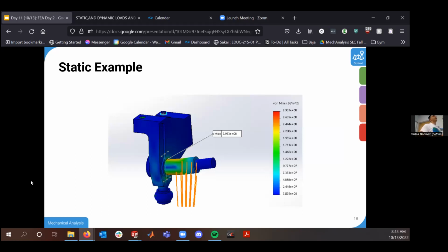This was a knuckle I did. Yeah, I very explicitly found that just for you. Here's a static load of a Baja knuckle turning, and we were looking at the spindle stress right there to see how much light weighting we could aggressively get away with. This is just a static case, which is not really the case you want for a moving vehicle, but for a pure static case, the stress is highly concentrated in the spindle and not the actual knuckle itself. So we could do a whole bunch of light weighting for that.